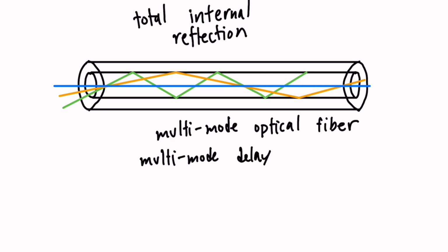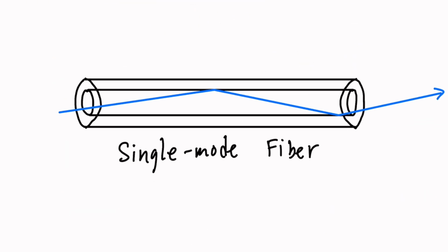One way to mitigate this is to limit the length of these multi-mode fibers to prevent significant distortion. Multi-mode fibers typically have a maximum distance of around 500 meters. Additionally, many long-distance fiber optic cables only use one mode, erasing this distortion, and this is called a single-mode fiber.